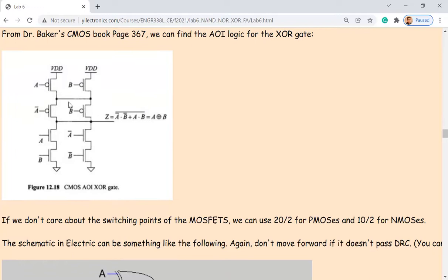So Verilog cannot reach that level, that bottom level. It's only handling, so if you look at the operators, these are only like AND or XOR. So these are gate level circuits. So you cannot simplify your circuit down to the CMOS level. You couldn't touch anything in the CMOS level.